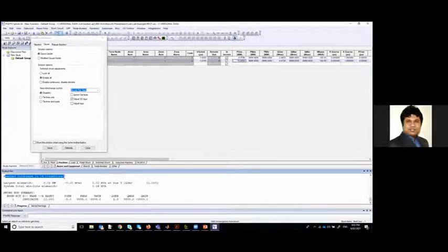But if your modeling is not right, it will say that it has terminated after a few iterations. That means the model you made is not correct. When it says the solution met tolerance, that means we got a solution.